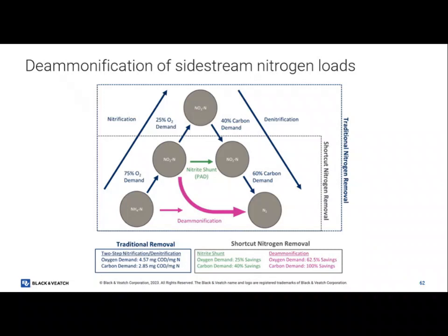This is aerobic. DO is actually inhibitory to Anammox bacteria, the red bacteria. So you start building on the layers of complexity here. Deammonification, this whole process here, the way the bacteria set themselves up is kind of neat. We want to have aerobic, and the reason the granules are so big is because of this.